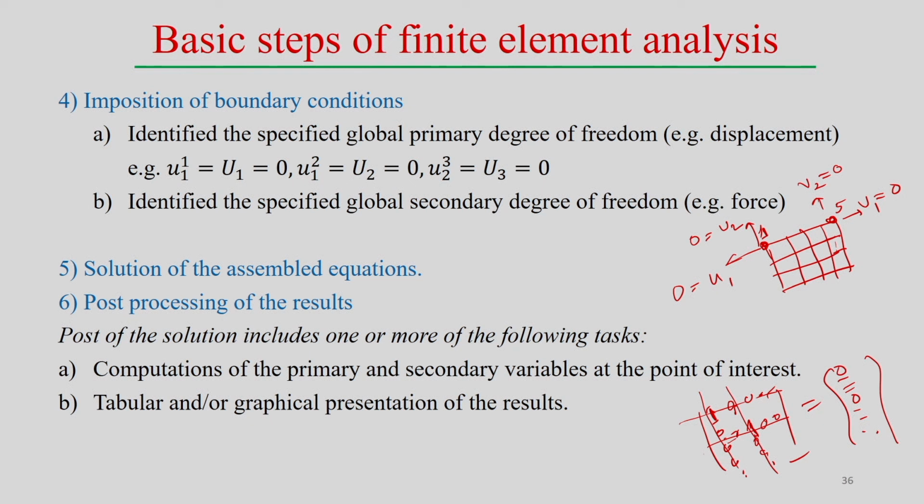Now, once we do this imposition of boundary conditions, then we go for the solution of the assembled equation. There are so many solution strategies, and we will discuss the different types of solution strategy, but finally we can solve this particular equation. Then once it is done, comes post processing of the result. Once the solution is done, we get the displacement field at each and every node point.